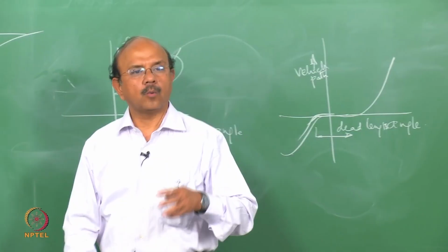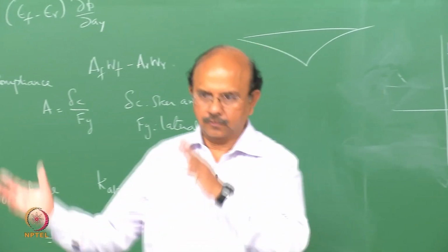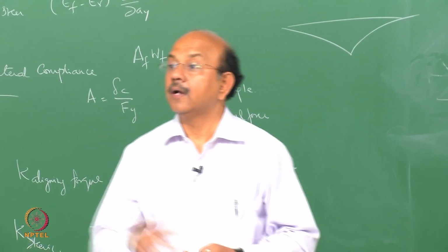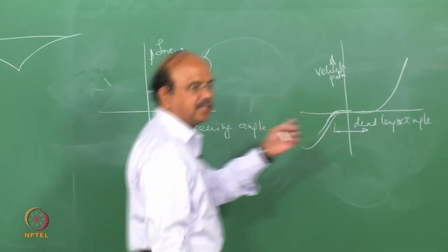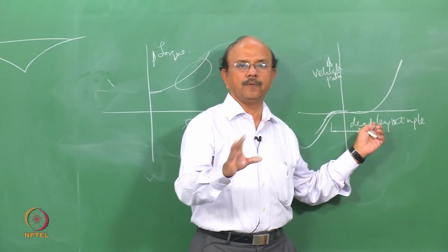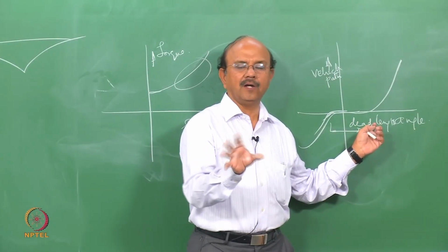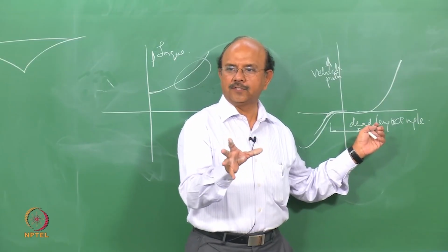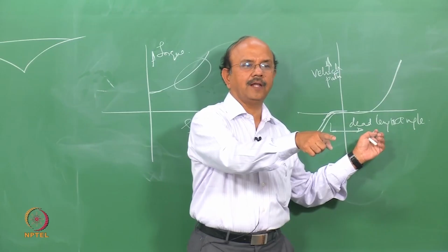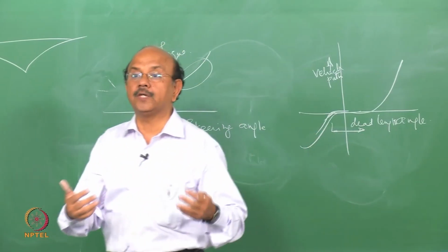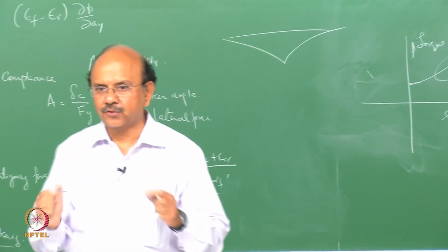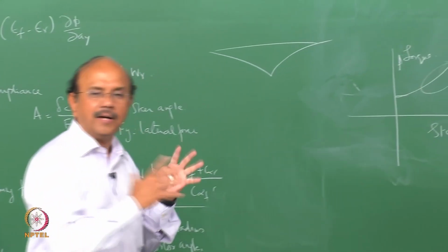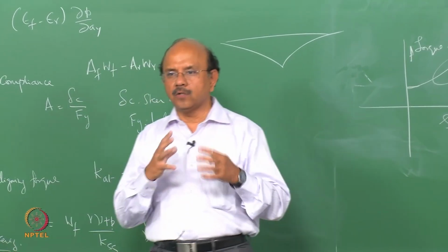Now, what happens if it is 0, smaller? Bring it to 0, right? Yes, that's correct. So if there are small disturbances in the road, it is going to have an effect on my steering, small vibrations due to that. Small disturbances are going to change my vehicle attitude or vehicle path, and hence I have to keep on adjusting it. So this is together the perception of the torque to the vehicle path. This is what is called the on-center feel.